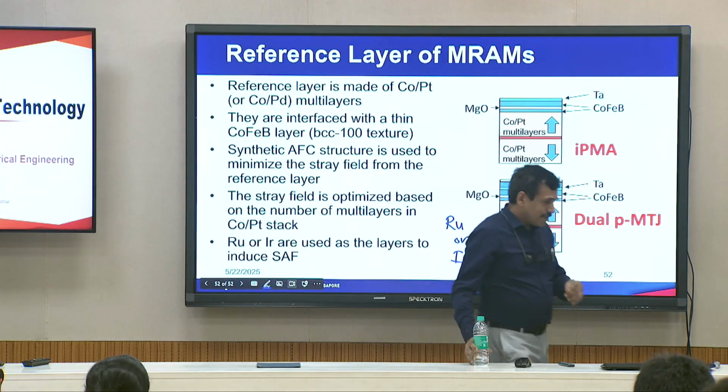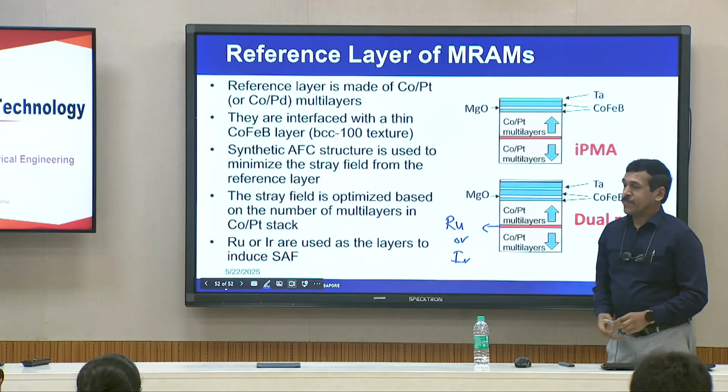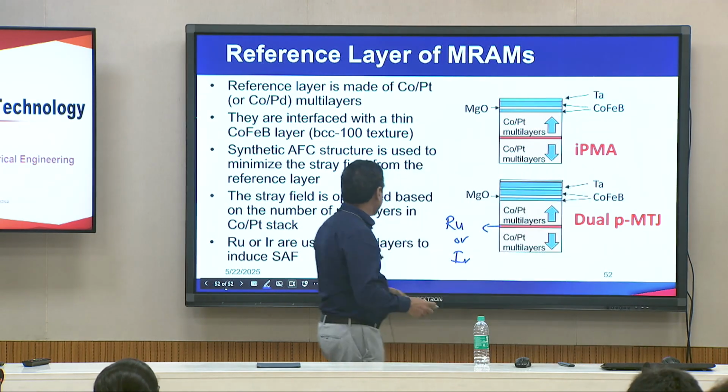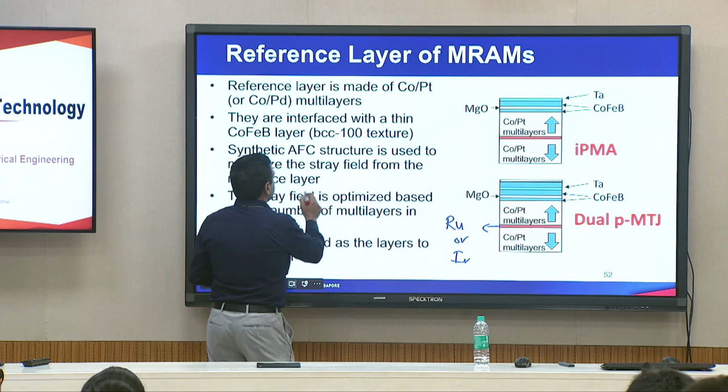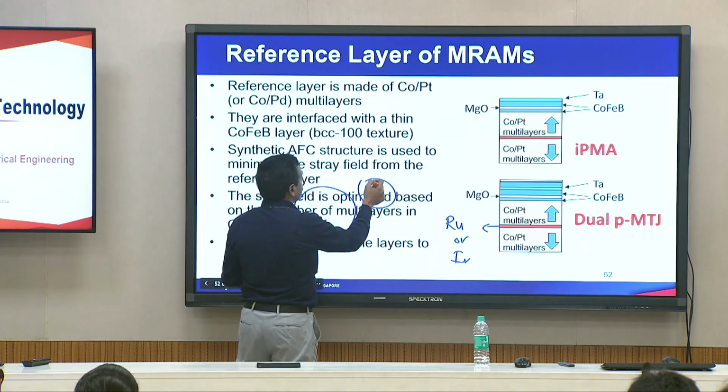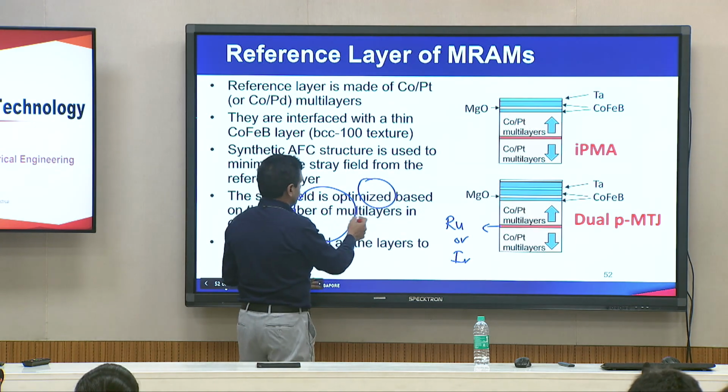Practically, doing this big structure, how is it done? In a single sputtering system, all these many targets are put on, a number of layers. The industry sputtering system usually will have a few chambers, at least 2 chambers. Some machines may have 3 chambers.